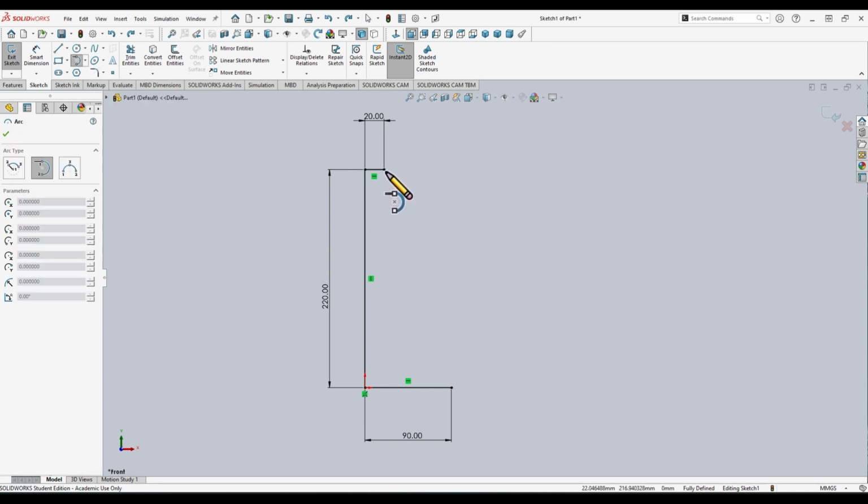And with this tool, I can click on this little dot here on the edge of my line. And when I left click on that, it's going to start drawing my arc as I move my cursor away. So as I move my cursor, I can see SolidWorks tries to make sketch relations for me right away to make my life easy or difficult, depending on what it's doing. So this first one that you can see here by these dotted blue lines is that it's trying to make a sketch relation of this arc at a 90-degree angle.